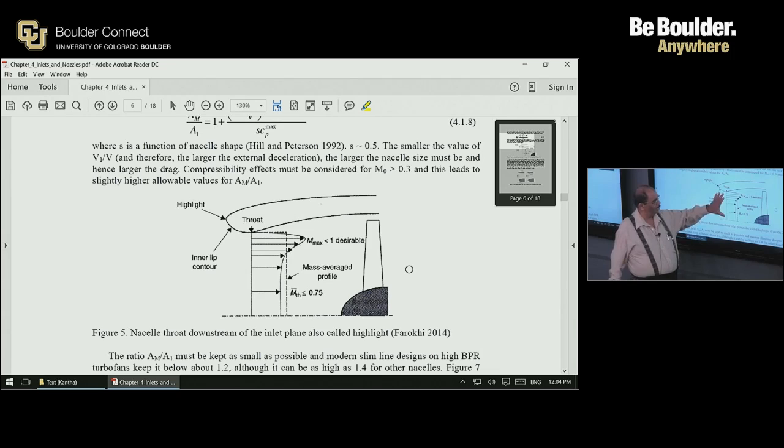But if the throat area is sufficiently small, then you can easily reach Mach number of 1. We don't want that, because once you reach Mach number 1, the flow accelerates further, and the diffuser section becomes supersonic, and of course has to be terminated by a shock wave. So that's not convenient. So the maximum Mach number at the throat section must be kept less than 1.